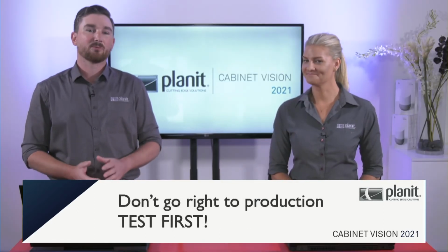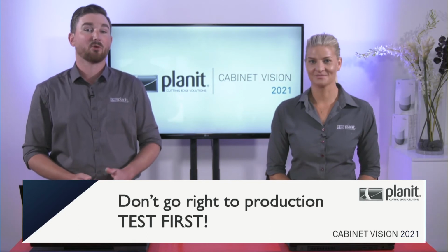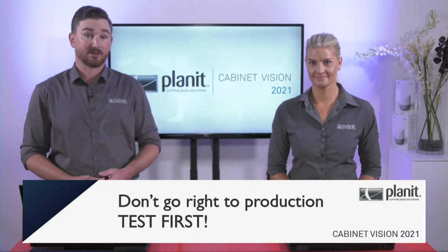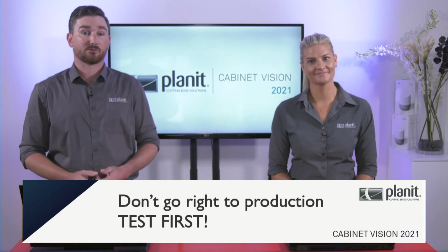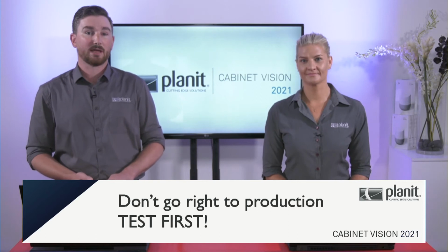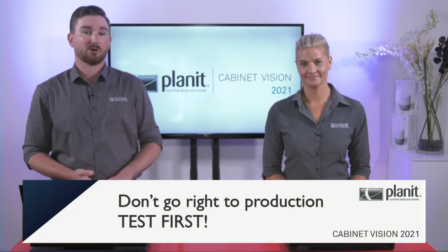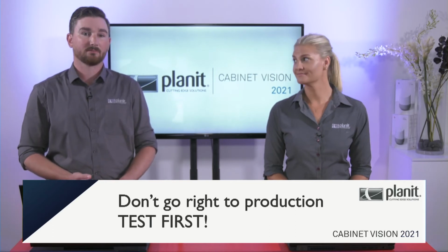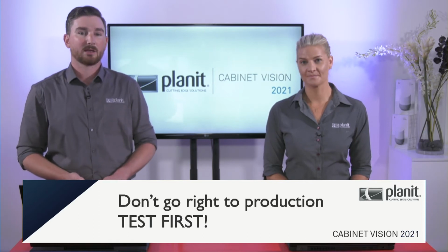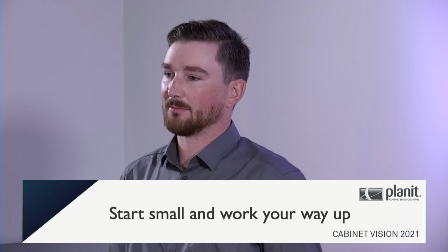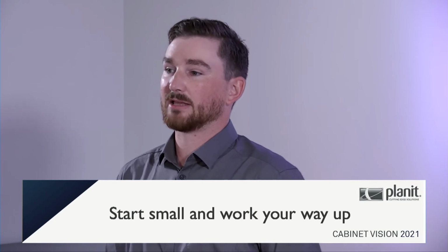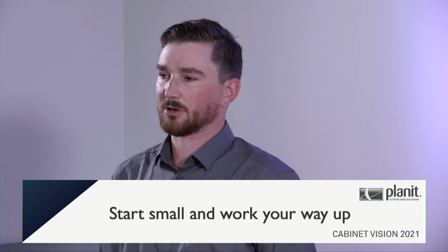Test first. We strongly recommend doing preliminary testing before migrating all of your licenses. Install the latest version at a secondary station if available, and run only small jobs through it. This is a fantastic way to trial new functionality, troubleshoot and check in on any custom work or user-created standards you might have without holding up the main production line. There are lots of updates in version 2021 that could have unexpected effects on your setup. Number 4, start small and work your way up. We recommend that once you feel like you are production ready, that you start by designing and manufacturing a small job before moving on to bigger projects.